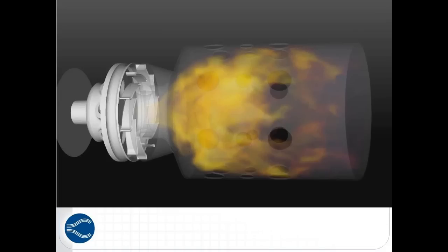And then I'll just answer one more question here. The question is, what kinds of mechanisms can you run in Converge? Perhaps I hadn't mentioned that before, but Converge reads in mechanisms that are in ChemKin format, so you should be able to run any of those mechanisms within Converge. And of course, I have to mention that you have to test the quality of the mechanism that you're using, because that's a key part of the simulation. But there's no special formatting you need to do with any mechanism in order to get it to work in Converge.